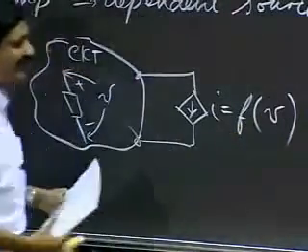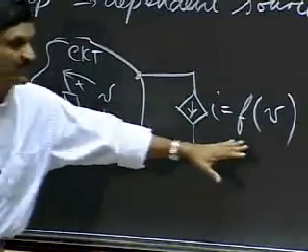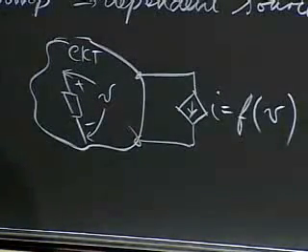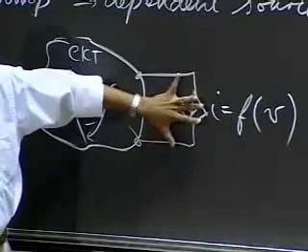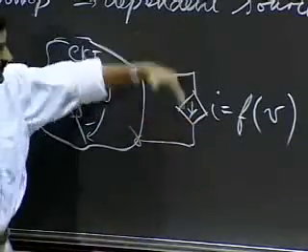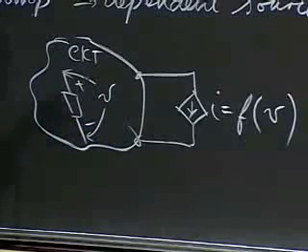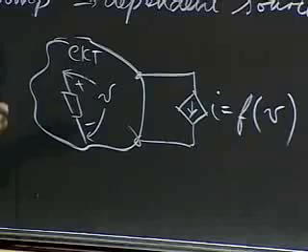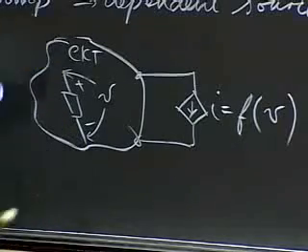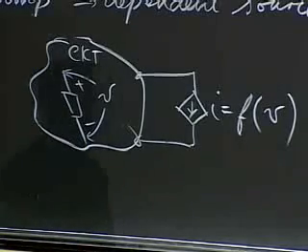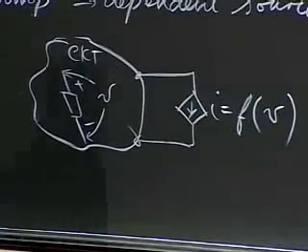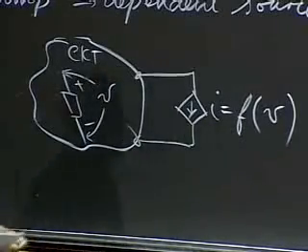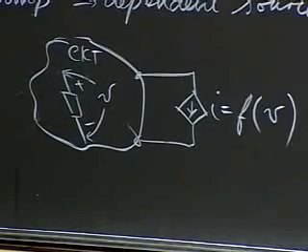And in this little example here, this current could be dependent on that voltage. Okay? So notice that although I showed you the 2 terminals of the dependent source that carried a current, there is another implicit port, another implicit terminal pair. And that terminal pair is called the control port of the dependent source, at which I apply a voltage or current that will control the value of the current source.